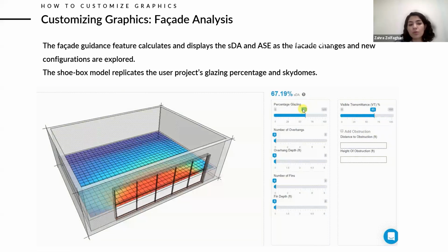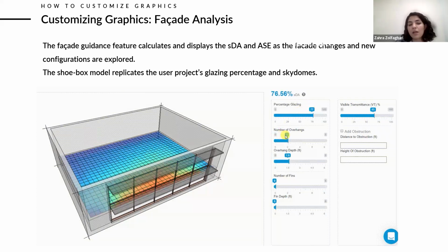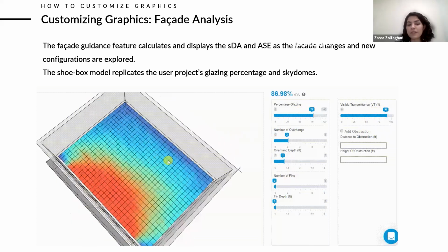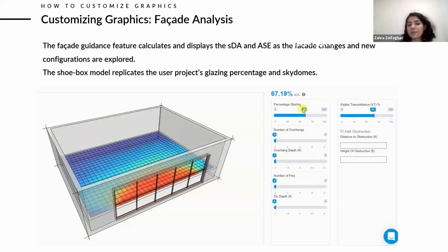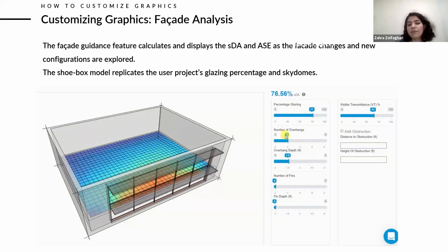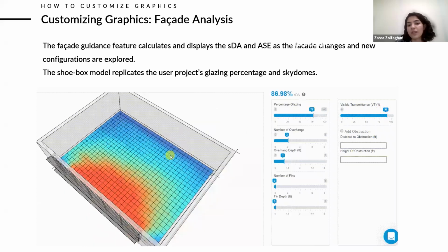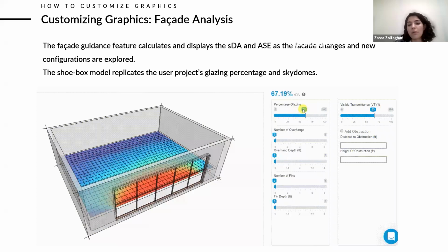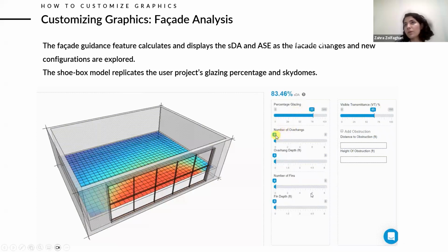We also have a facade tool, which is a rapid prototyping tool to test and validate different facade strategies, different window and shading device configurations. So users can customize the graphics they can get from this page in order to better understand the spatial quality of the room based on their facade design. As you can see in this GIF, you can add windows to each facade of this room in different cardinal directions. And then you can change the window to wall ratio and add shading devices to each window. Actually not all the controls are included here, but you can see them on the next page.